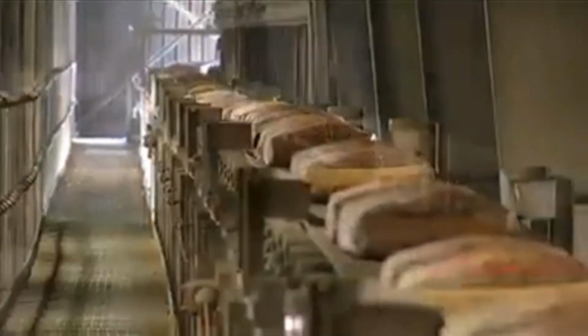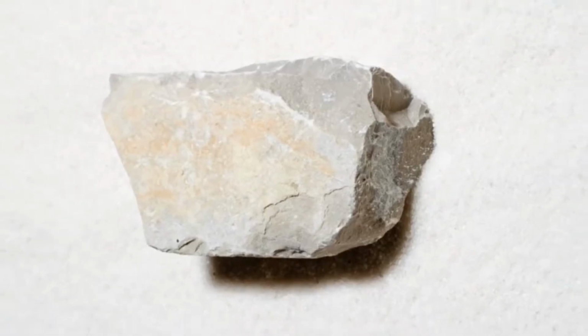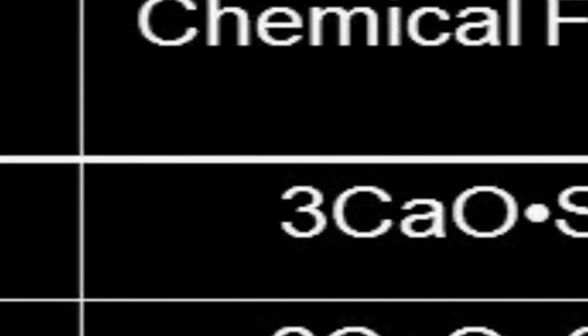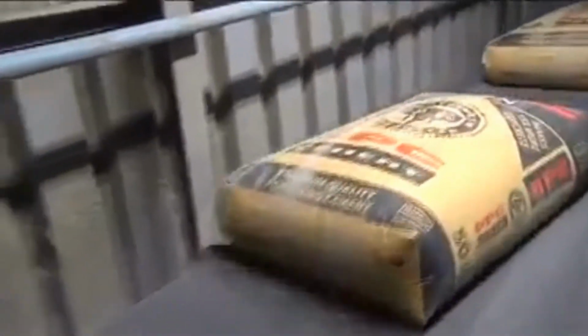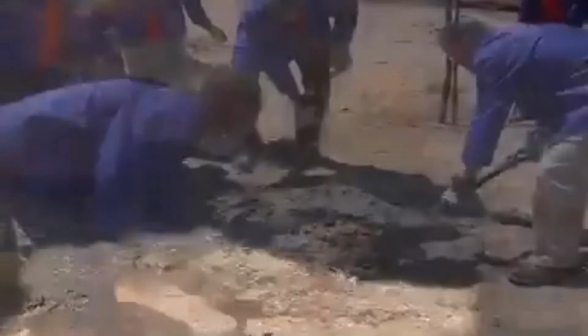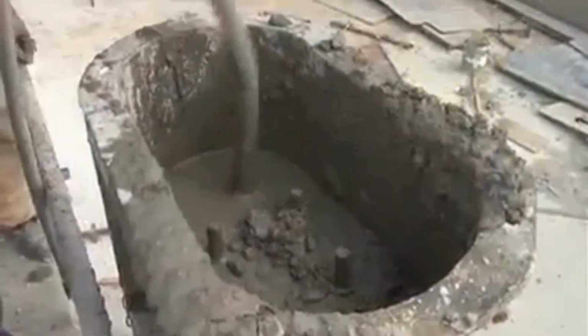Portland cement is made up of Portland cement clinkers and gypsum, and it will produce tricalcium silicate. Portland cement clinkers are made up of three raw materials, which are limestone, clay, and also marl. Tricalcium silicate is the major constituent of Portland cement, so we need to make sure that tricalcium silicate production is at a higher amount. We need to consider two things. The first one, the mixing ratios of raw materials should be appropriate, and the adjustment of the lime content must be accurate.